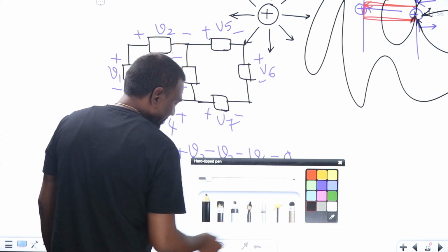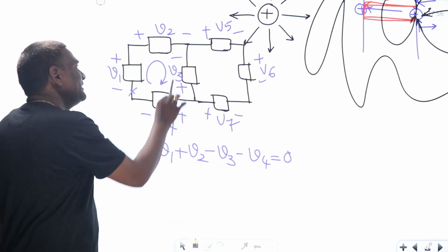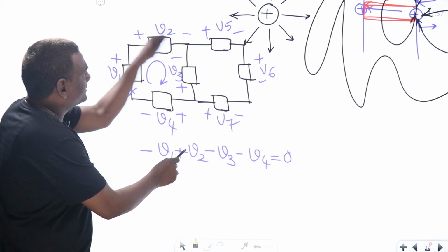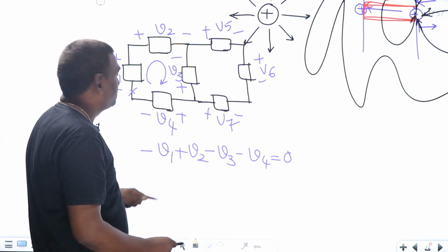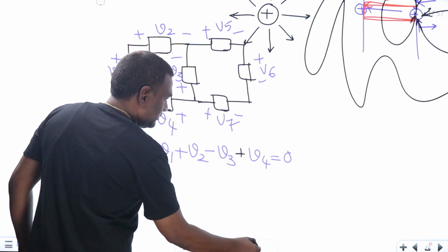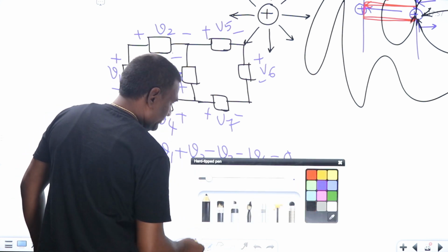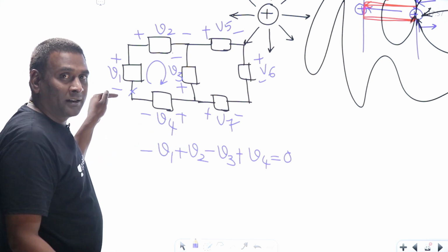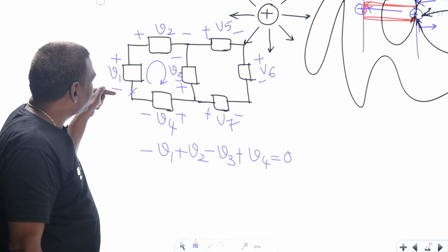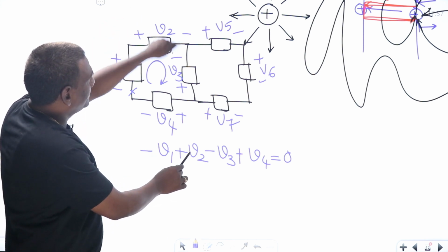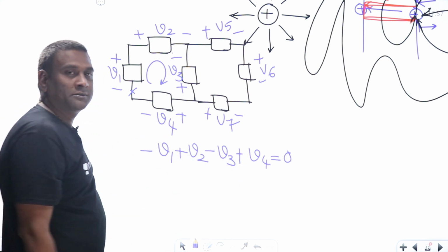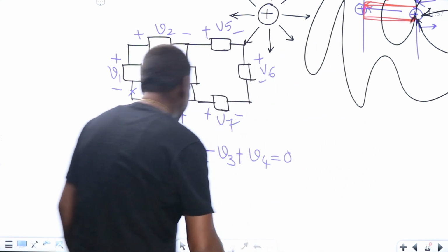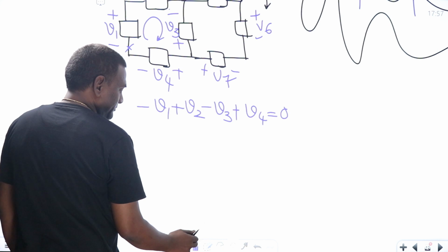Now, let us see the same equation again. Very simple. In applying the KVL, I touched minus first, then minus, then plus first, then plus. Sorry, it should be plus. I'm sorry, because it's voltage drop. If you recheck the equation, minus I touched first, minus; plus I touched first, plus; minus I touched first, minus; plus I touched first, plus. This is the algebraic sum of voltage drops in a closed path equal to 0. We are going to consider this. Interlinking between this we will discuss later.